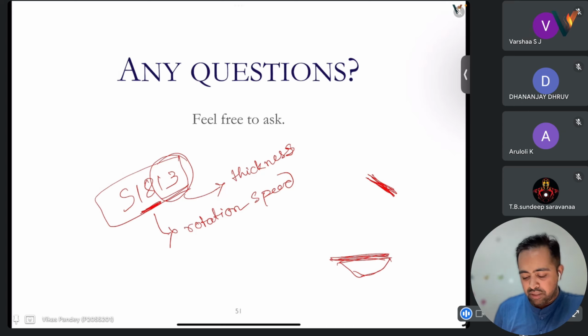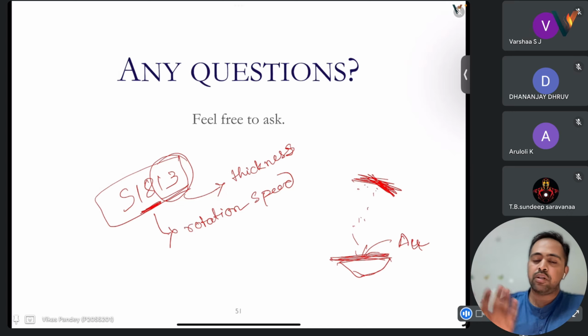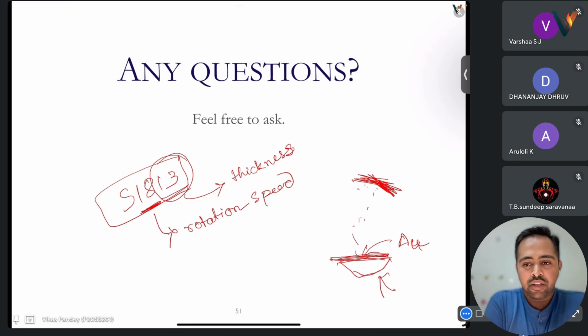Here you have a metal, say gold. You heat it to such a high temperature that it evaporates, and your sample is put here, so it will go and stick there. So it is deposition by evaporating your material. Fine. Oh, okay, sir.